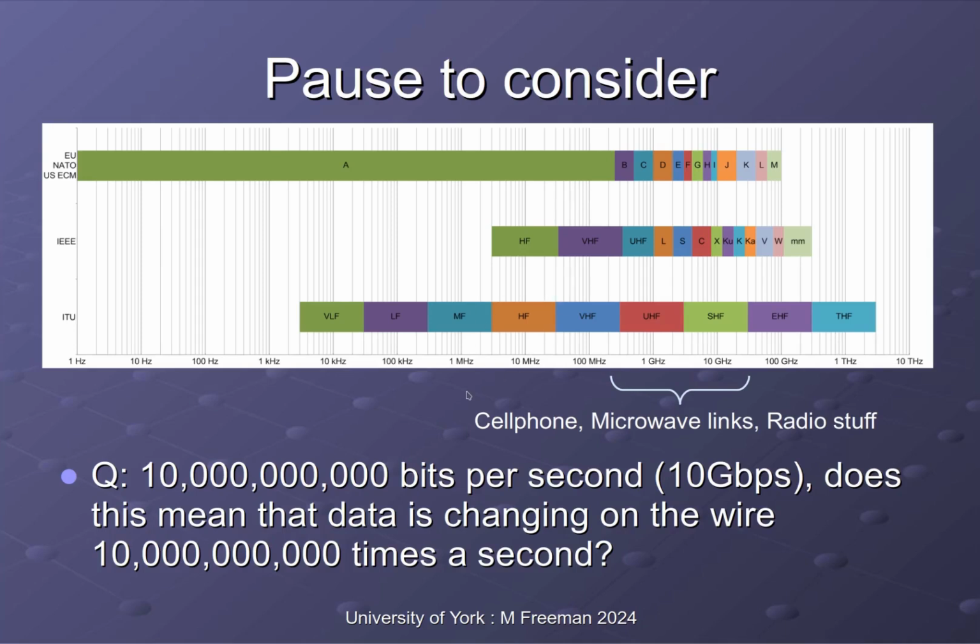So frequencies around about 10 megahertz, that's normally kind of okay. And you see that back in the day when we had 10 base 2. We could send our Ethernet data quite happily down 200 meters of coax cable, and you could still receive the data at the other end with some cheap and cheerful hardware without going too exotic and specialized. However, as we want to transmit more bits per second down our cables, obviously the frequency components will increase.